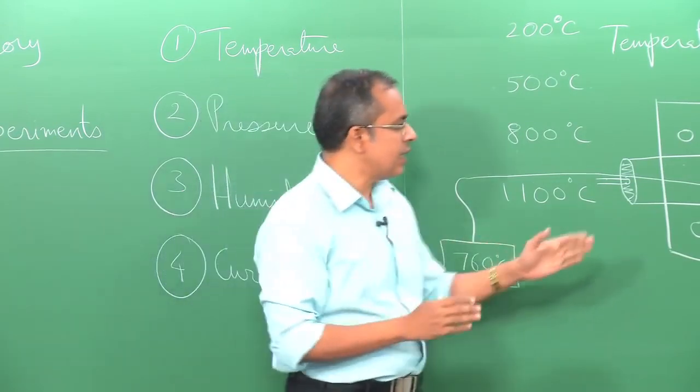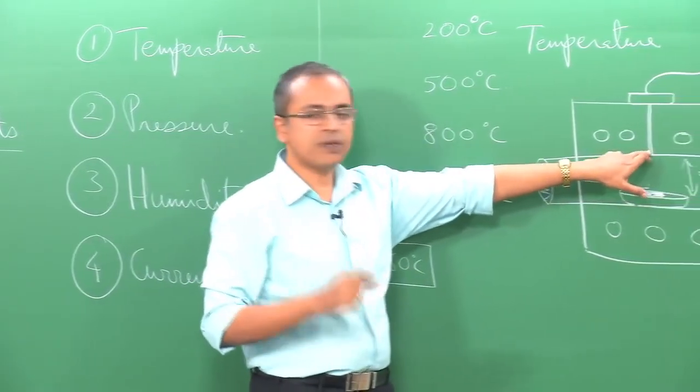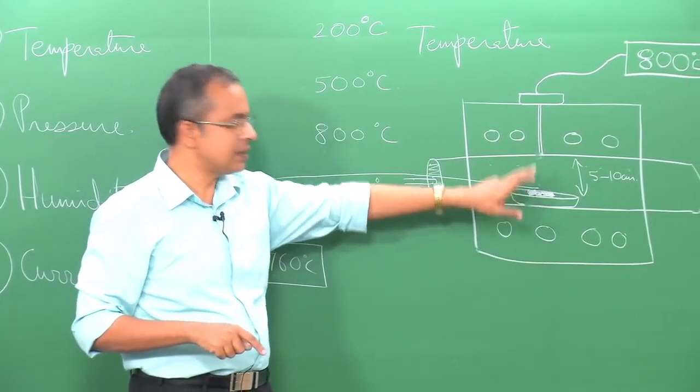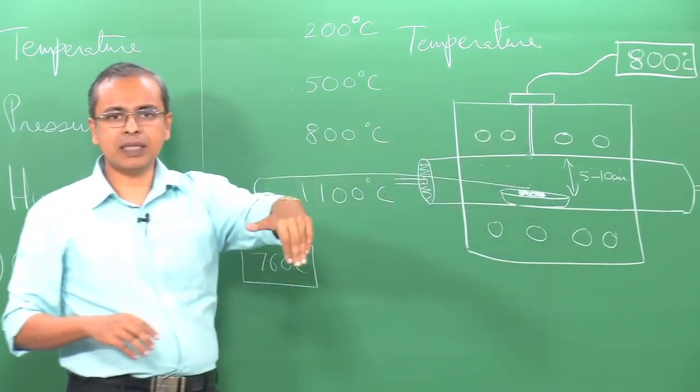And when you understand that, you can figure out if there is a scope for error. So, here we figured out that the location of the thermocouple can give you a wrong idea of what the temperature is, because your sample is sitting somewhere else. So, this idea may not be exactly the same for some other measurement.